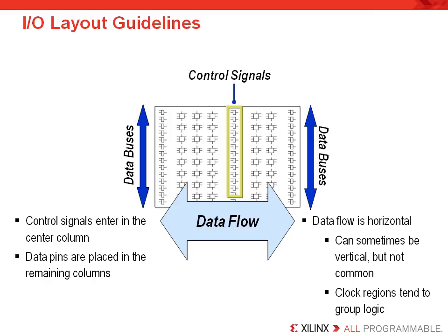We also want to emphasize that design layout usually transmits signals left to right or right to left along the FPGA, and very seldom do signals transmit vertically going up or down. This is because the bit ordering of the carry logic resources propagates the carry signal vertically upward.